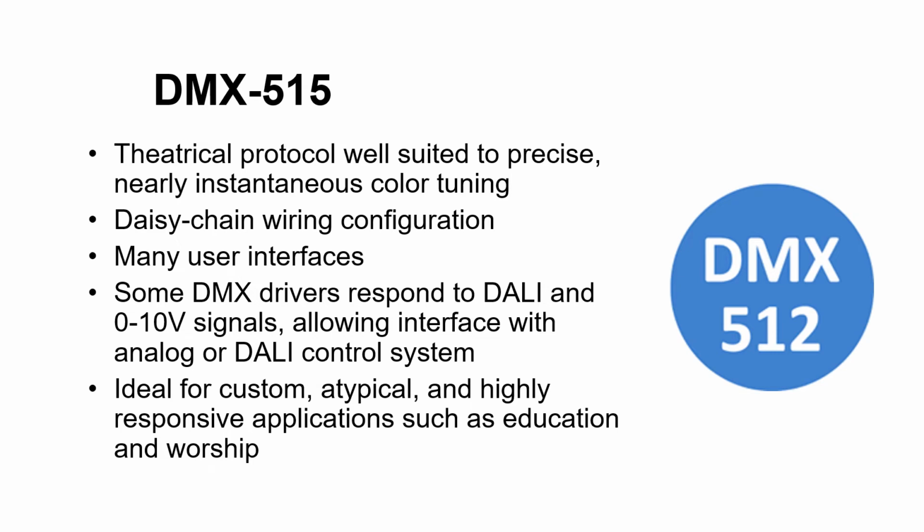DMX signals can also be used internally in Tunable-White luminaires using multilingual drivers, even when the user interface is 0-10 volt or DALI. This allows the Tunable-White luminaire to respond very quickly while participating in a DALI system. DMX applications include theatrical, education, houses of worship, and custom or atypical applications that require a very high degree of responsiveness and precision.